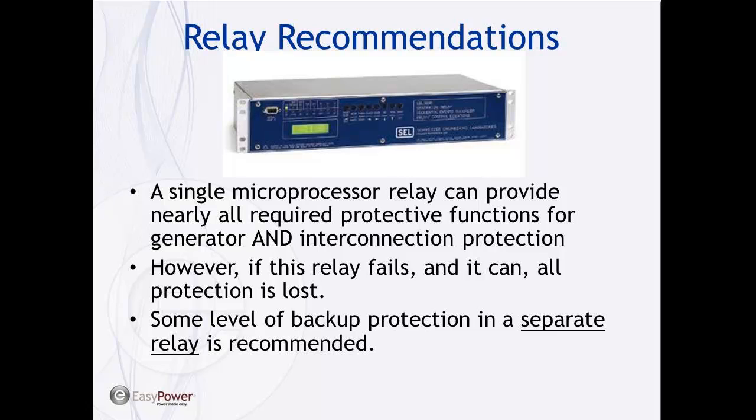Or you may go to something a little less elaborate, but you're going to need a separate relay that can provide some backup protection. So ideally your backup relay would connect to a separate set of CTs in case the CT fails, but one way or the other you do really want to have a backup relay of some type.